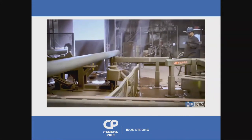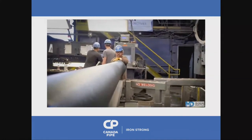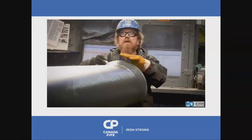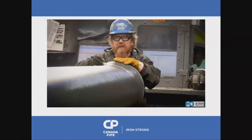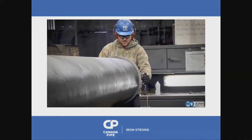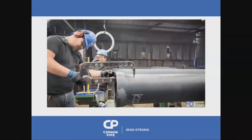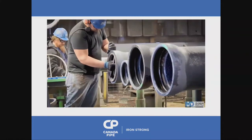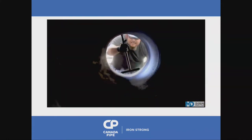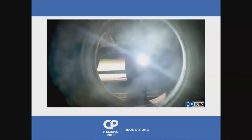And then it goes down to more testing, and we actually will look at all the pipe and we'll check the batch numbers. We will be testing all of the ovality. We will be testing thickness, which you can see right there. That's the internal diameters that they're testing in 3 different places. So it's very involved as far as what we do.